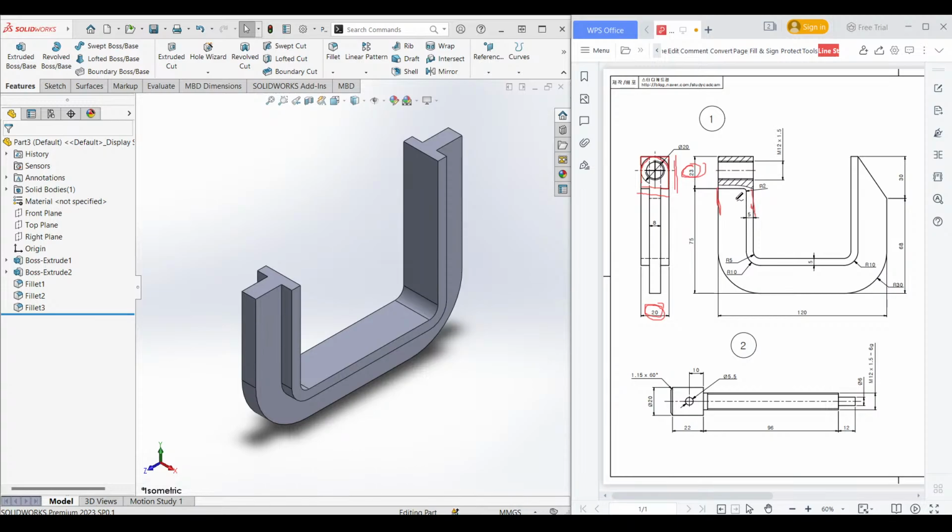Okay, let's go back to our sketch, and before that we can see we have a circular profile here, and this circular profile has a total dimension of 20 unit, and in the inner portion we have an M12 1.5 extrude cut hole. We will also do that. So let's go to our sketch.